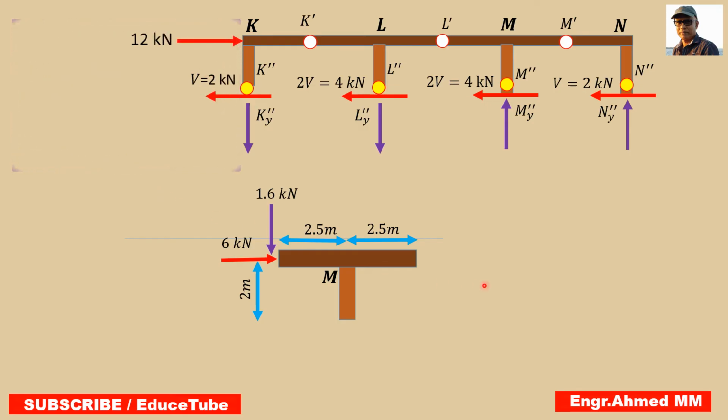Now at this position and this position we have to think. First of all we bring this 4 kilonewton. Already there is a shear force here, so we can bring this 4 here. Now we need to find these horizontal reactions components. How to?